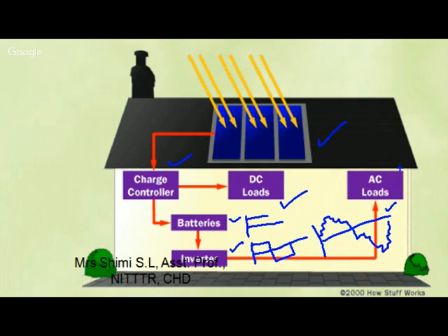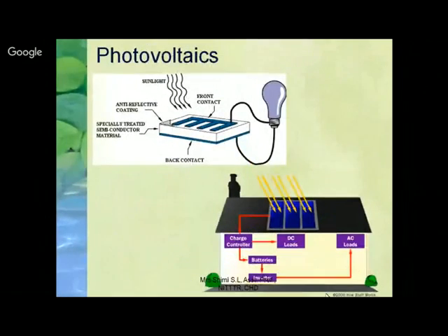If the load is not so important, a 2-level inverter or a 3-level inverter is possible. For a 3-level inverter, first we get the DC, then we have 0, and then again the negative. This is also almost similar to an AC waveform. This is a 3-level inverter, but this one is a 2-level inverter. You can go for even multi-level inverters.